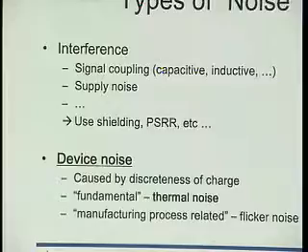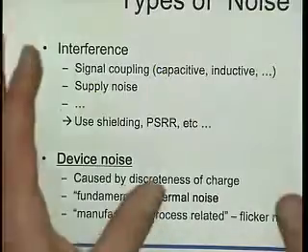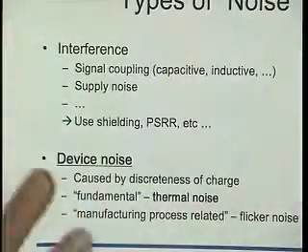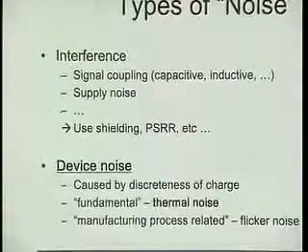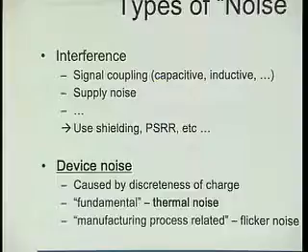Very often we're going to talk about other forms of noise now, right, for weeks. And you're going to build an IC, and you're going to do all of this, right, because I'm going to flood you with that thermal noise business, right? But then in the end, the actual problem is perhaps going to be an issue with the pad frame. You put bond wires too close to one another, so okay. So, of course, long buses also can couple capacitively and so on.